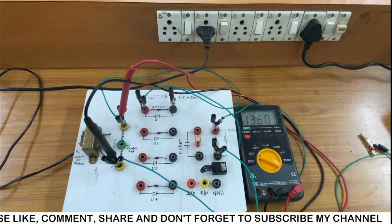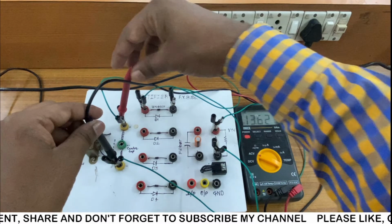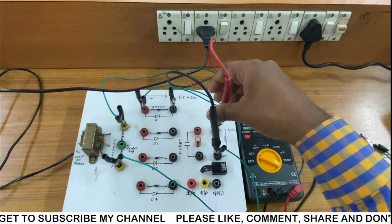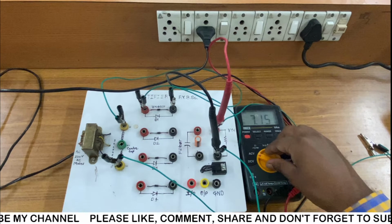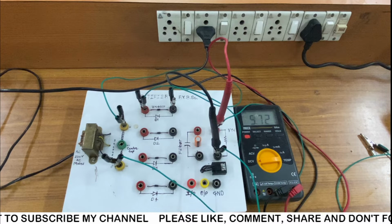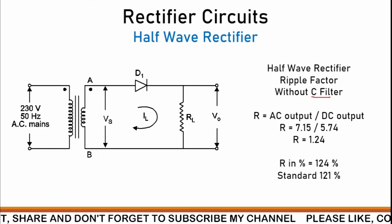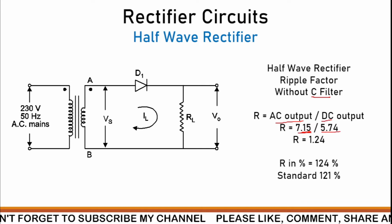So this is the half wave rectifier. You can see here, I have connected the half wave rectifier and I am measuring the AC at input, and now I am measuring AC at output. The AC at output is 7.15. If I measure DC, it is 5.74. These two readings are necessary to calculate ripple factor. Without the C filter we are doing the experiment, where we are getting AC output of 7.15 volt and DC output of 5.74.